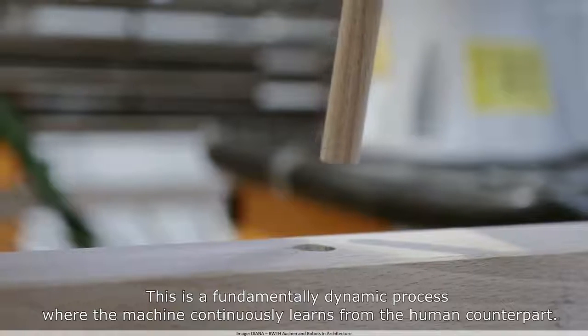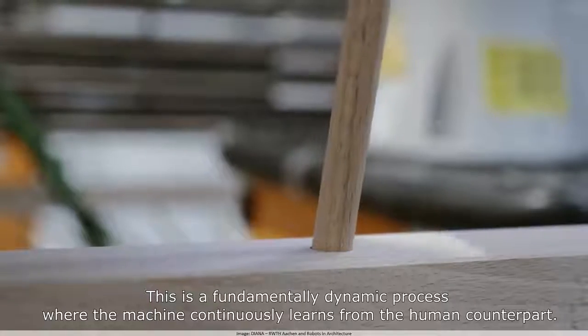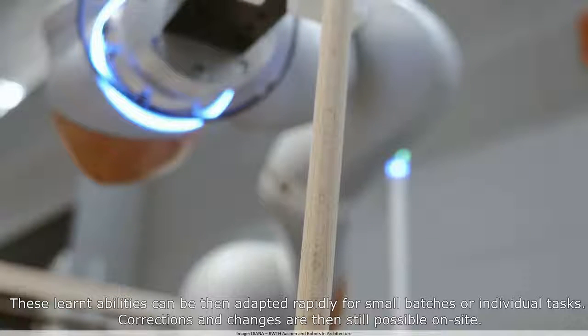And the assembly works a bit similar to how we do it by hand, because we looked into how you assemble by hand, and actually just looking at it isn't really enough information to put something like that into a hole. So we usually get the rough information by looking at it, and then we assemble by feeling. And we did the same here, but we didn't have a camera system. Instead we had our ideal 3D model that told us this is where it's supposed to be, and then the robot, with its sensitivity, adapted to it in real time. So it just meant this kind of zigzag movement, and once it slipped in, it knew it's at the right position, and it can release.